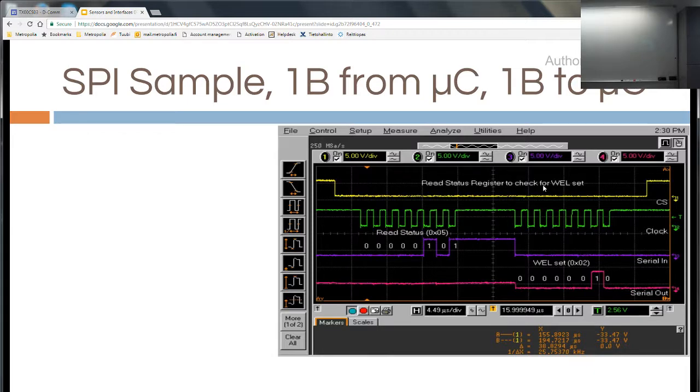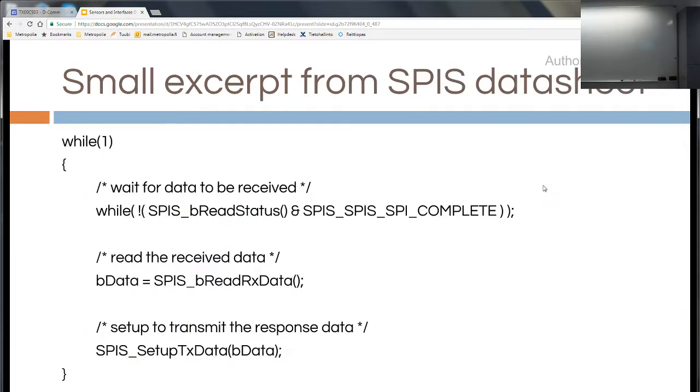So while you are writing, the device is also setting something on the MISO bus. And what it actually has here is what the device gave during the second byte. So this was the command byte, and then the device answers. Something like that.